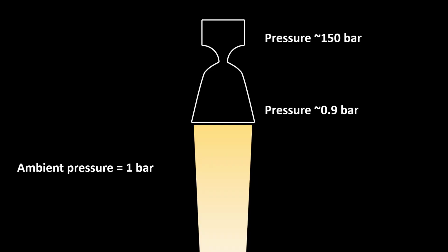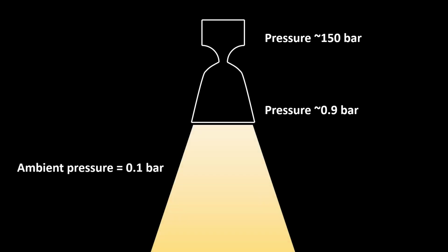Rockets get propelled by mass flowing in the opposite direction. In the atmosphere of Earth, the exhaust plume stays contained by the ambient pressure of the air around it. But in the higher layers of the atmosphere, the ambient pressure is so low that the exhaust plume starts to expand sidewards and grows dramatically in diameter. And due to some exhaust being sucked away to the side of the plume, the generated thrust decreases along with the engine's efficiency. Nozzle expansion defines the pressure at which the engine exhaust leaves the engine.